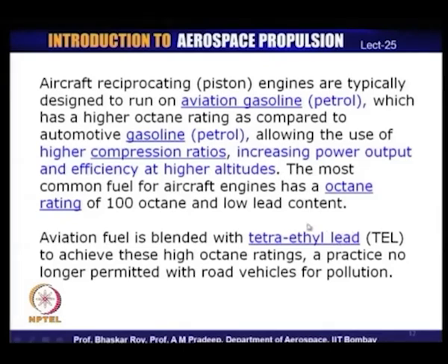In land based automobiles, this addition of tetraethyl lead is now banned because of environmental issues, but in aircraft engines it is still being practiced, because aircraft mostly fly at very high altitudes, and we require the high octane rating that is necessary to operate at very high compression ratios at high speeds for producing high power at reasonably good efficiencies.